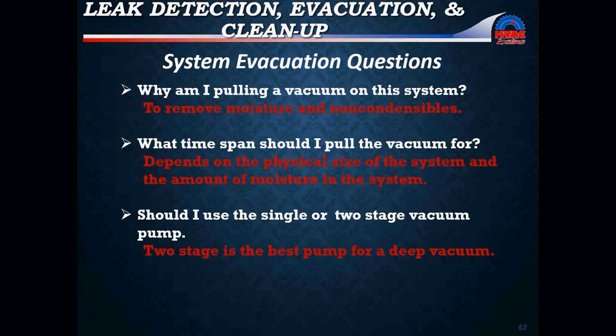Why am I pulling a vacuum in a system? Well, it's pretty simple. When we pull a vacuum on a system, we're doing it to remove moisture and non-condensables. That's the main purpose of putting a system on a vacuum pump.